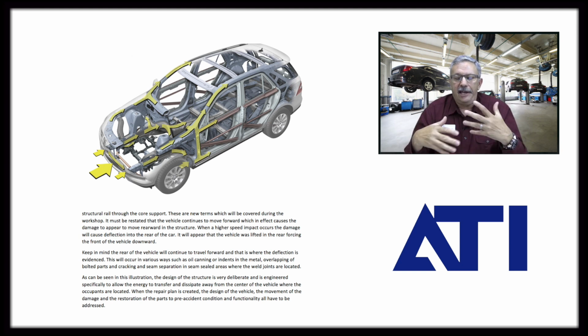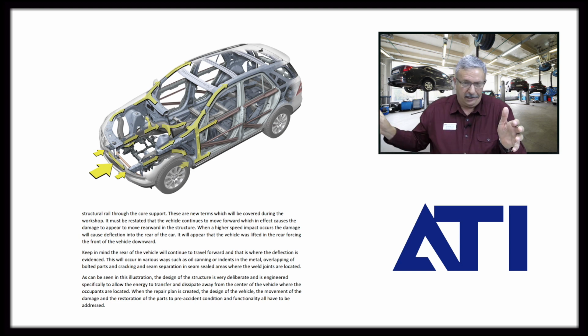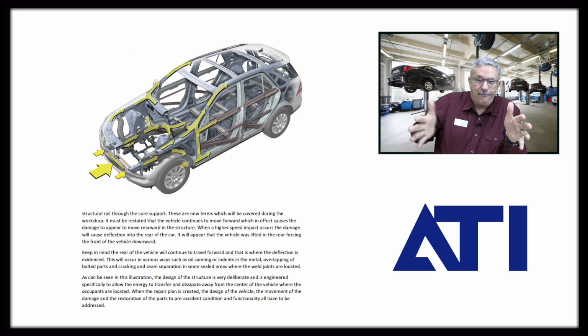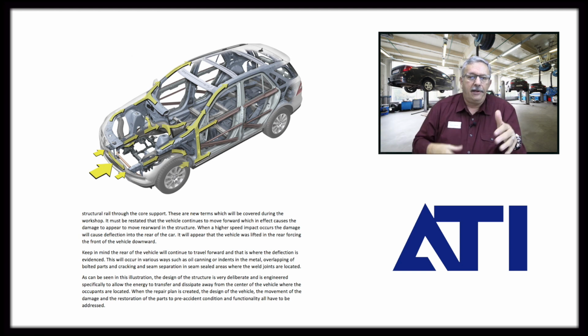So again, we're going to cover a lot more of these things in greater detail, but it's really important to have a firm understanding that the damage just doesn't stop in the area of direct damage. It's going to continue going till it loses its energy. And we have to remember, where it lost its energy is the first place you've got to check for damage, so that I can pull that damage back out in a way that will restore the structural integrity back to the vehicle.